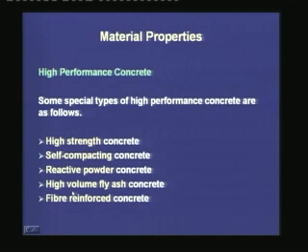The high volume fly ash concrete uses the industrial byproduct of fly ash. It has several advantages. First of all, it has reduced shrinkage cracks. Although it gains strength slowly, over time it may achieve high strength. And the fifth type of concrete is the fiber reinforced concrete.